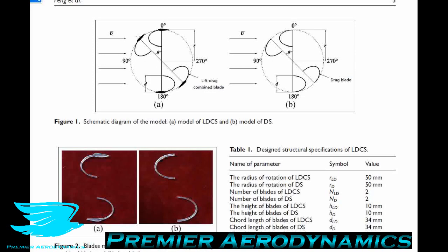So, for example, we have the flow coming in, it hits the front of this front airfoil, and because it's at a 0 degree angle of attack, there is no lift being produced. Similarly, when the airfoil is at 180 degrees, there is no lift being produced because, again, there is no effective angle of attack here. So to produce appreciable lift, the airfoil profiles need to be pitched a little to the oncoming flow.